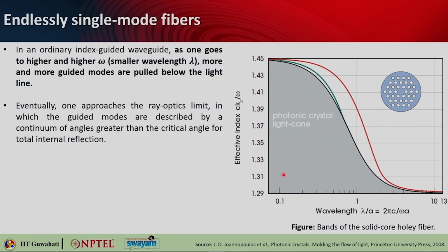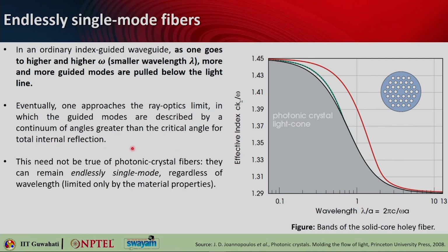But in the solid core holey fiber, when you reduce the wavelength or increase the frequency, the effective index basically touches that of the silica. So they can remain endlessly single mode, regardless of the wavelength. That is something very interesting: in this particular case you can have single mode throughout.